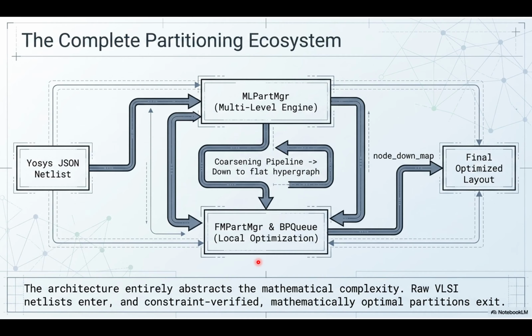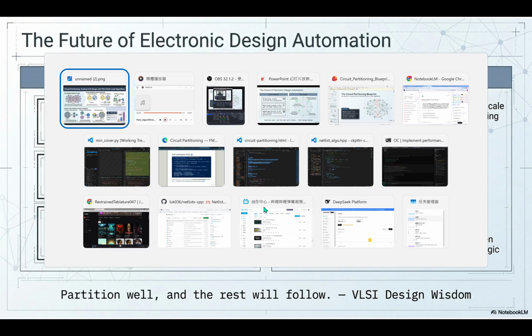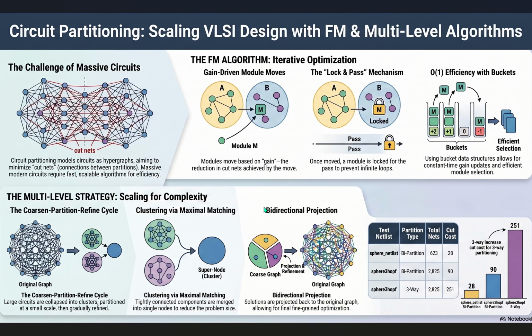That is brilliant. Okay, so to synthesize the whole engineering pipeline we've talked about today, we start with a staggeringly complex hypergraph that accurately reflects the physical wiring of a massive system. Right. And because standard flat FM partitioning just gets trapped in local minimums, we deploy a primal dual matching algorithm to coarsen the graph, mathematically ensuring we absorb those dense neighborhoods into supernodes. We compress the complexity. We deploy min-hash signatures to deduplicate the hyperedges in constant time. We run the O(1) bucket data structure to partition the macrograph, and then we refine it back to its original state. It is an incredibly robust chain of logic designed to completely tame scale.